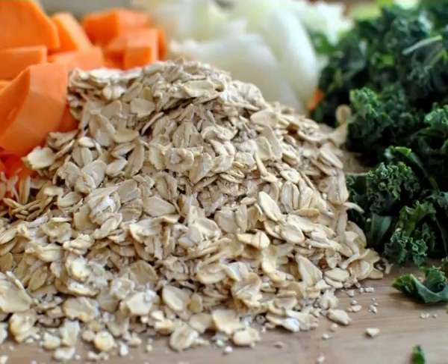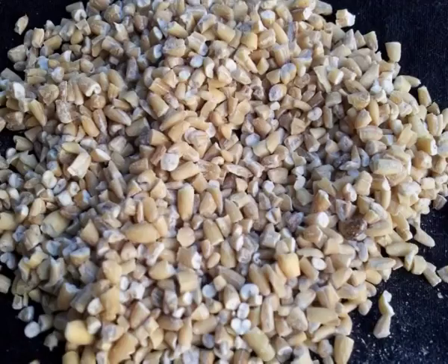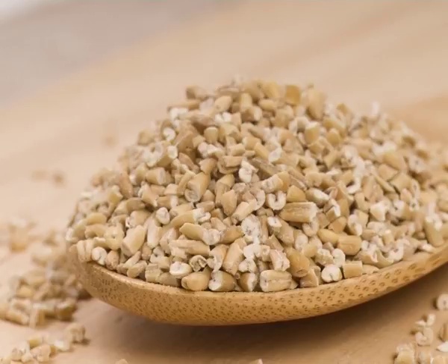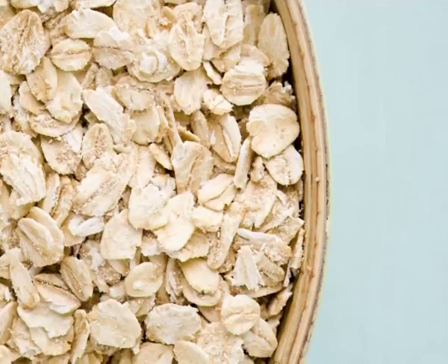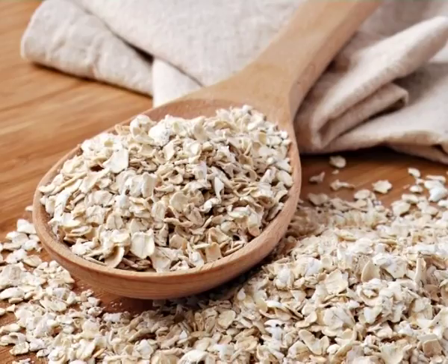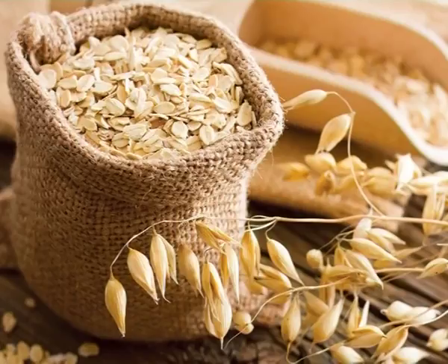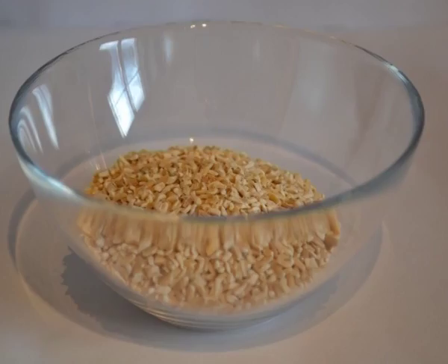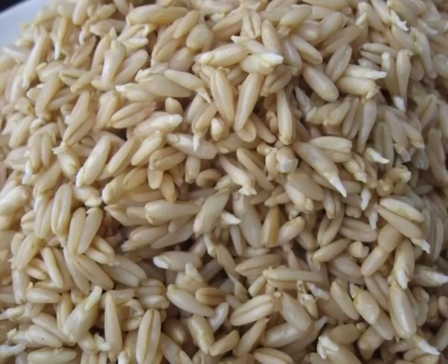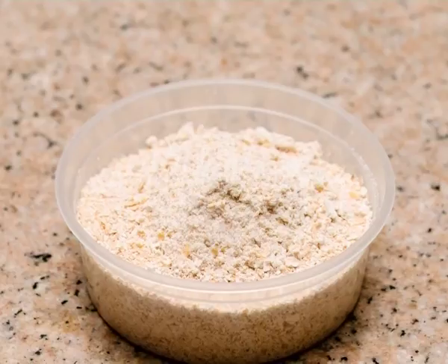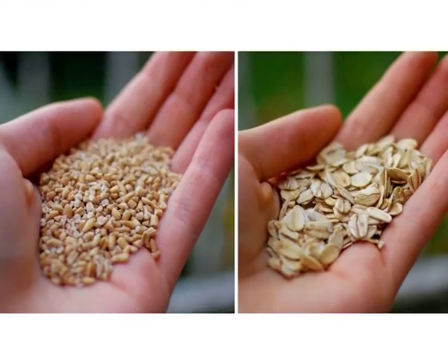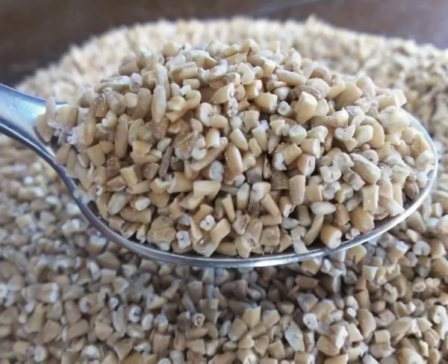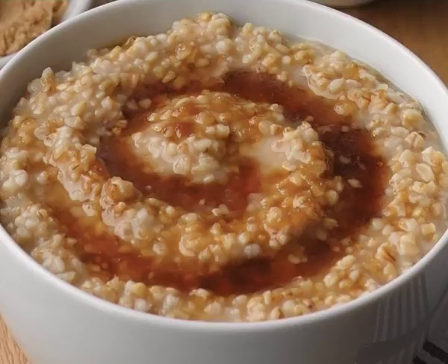In milling, cleaned oats are subjected to kiln drying to inactivate lipase. This process is known as stabilization. Stabilization also reduces moisture content and facilitates the subsequent shelling of the oats. The kiln-dried oats are then shelled, resulting in the splitting of the husk. The shelled groats are then polished, and after removal of oat dust, they are transversely cut so that each kernel gives about 4 to 5 pieces, that is pinhead meal. This is subjected to further grinding when oatmeal is obtained.